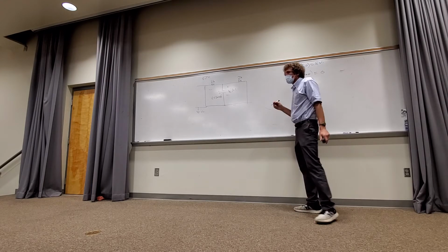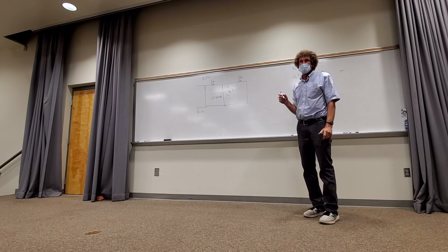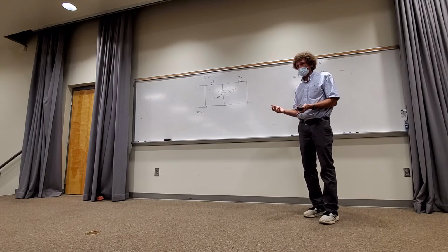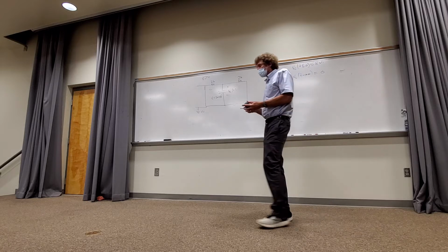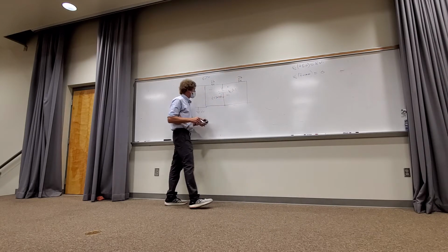We're getting there. Now what's the next thing we have to do? Do you remember? We need to find the Thevenin equivalent resistance across that capacitor, as if the capacitor is the load, right? Do you all remember this, class? And somebody brought that to my attention that it is as if the capacitor is a load, right? So what is that Thevenin resistance going to be? Just think about it. What resistance is across those 2 terminals?